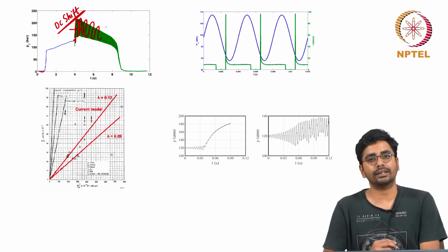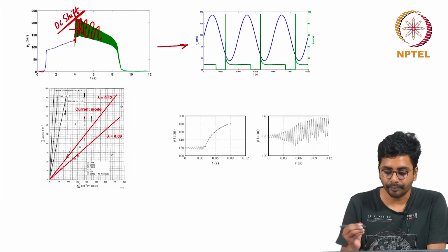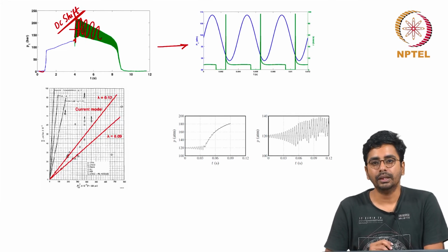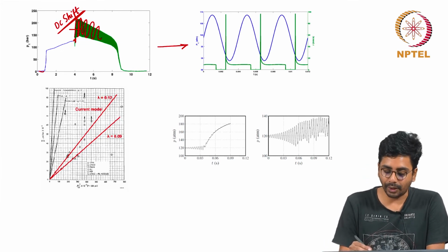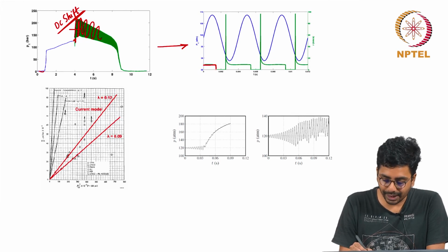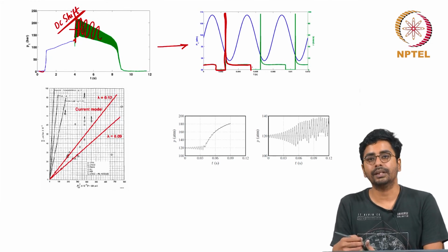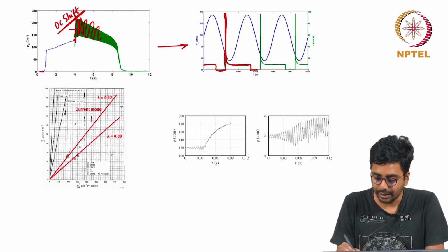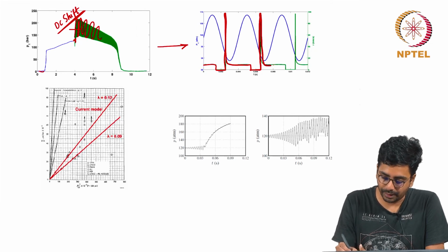This is a characteristic of solid rocket motors, and we saw that during the DC shift the propellant is subjected to very high depressurization and cyclic depressurization and pressurization phenomena that cause cyclic extinction and dramatic reignition, where the burn rates can go to 10 times the mean value before it comes to the mean position, quenches again because of high depressurization rates, remains quenched and ignites dramatically and comes back.